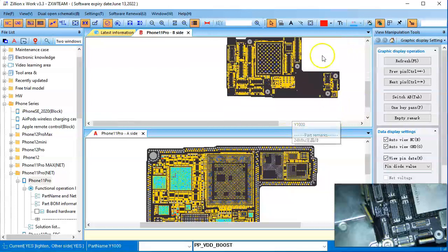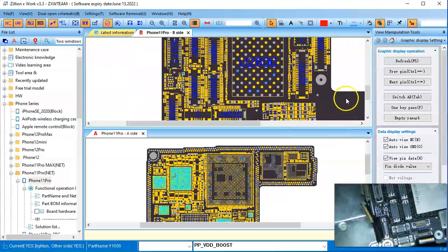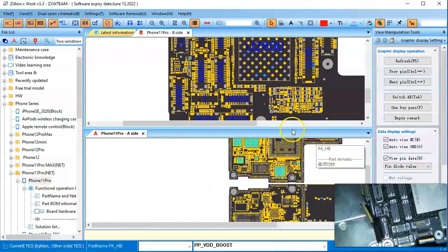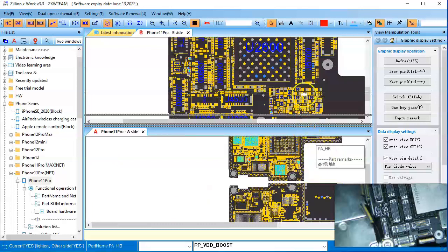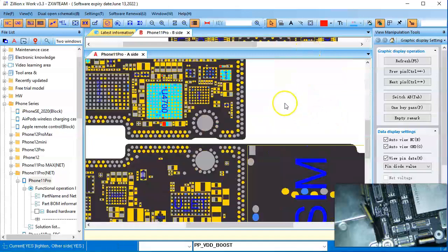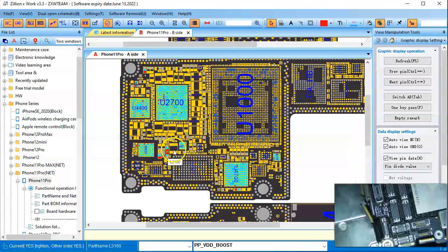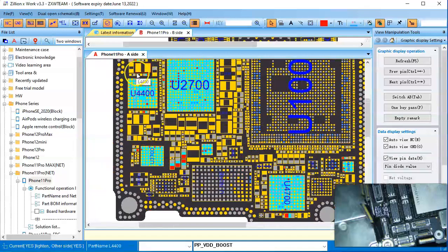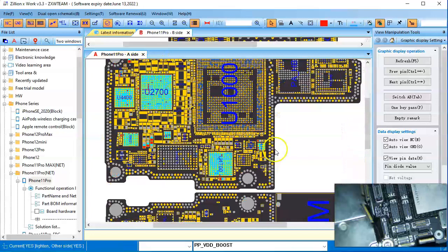Other than that, there's really nothing else on the top front of this logic board that could be shorted. So most likely the issue is going to be on the other side of the sandwich, unfortunately. Most likely it's going to be one of these big caps, and this should be fairly simple because look, there's only 1, 2, 3, 4, 5, 6 big caps here.